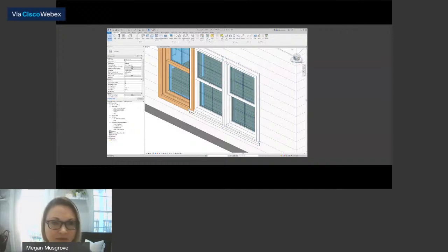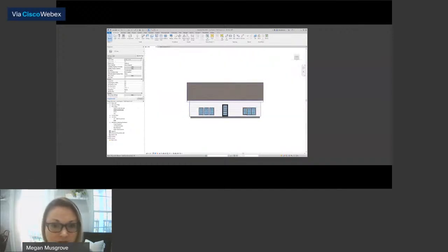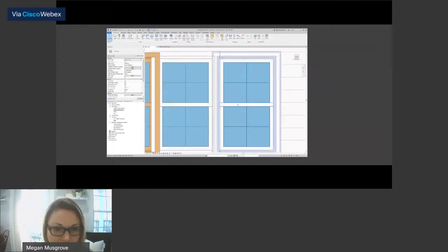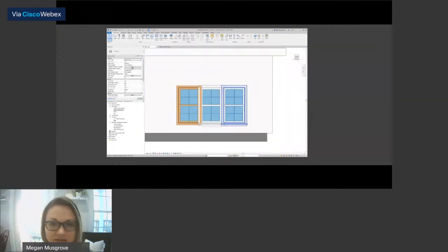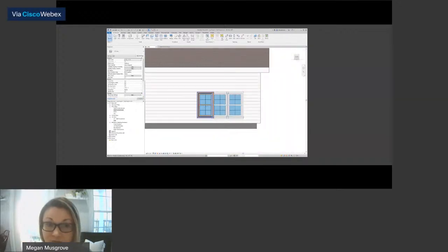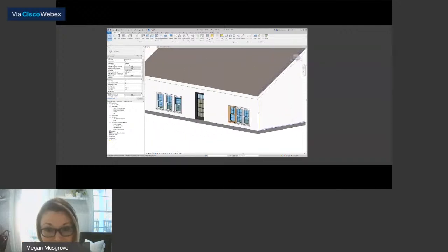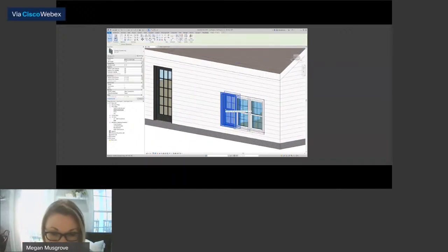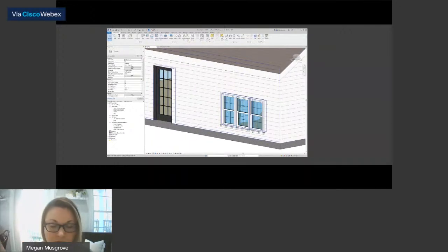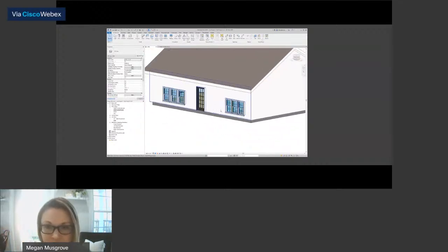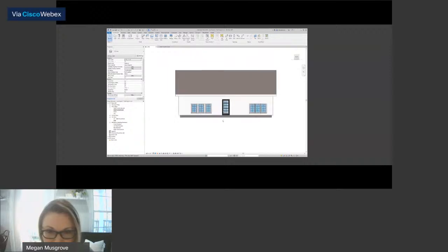If I look in an elevation view or the 3D view and I can see, oh yes, the top is on the outside, then that is the correct way. So this one is inside out. How do we fix it? Just click on it, hit the space bar, boom, it's right where it's supposed to go. Now, these are in a horrible, disgusting, ugly position.